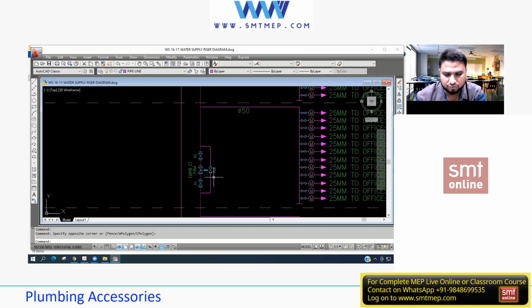First of all, I need to find out the distance, or the height or the length over here, then put it into that. But there are some conversions, because here these things are in metric, that is millimeters. I need to convert that into feet. First of all, you people write it: P equals H into 0.433 psi. That is pressure, to find out the pressure exerted.